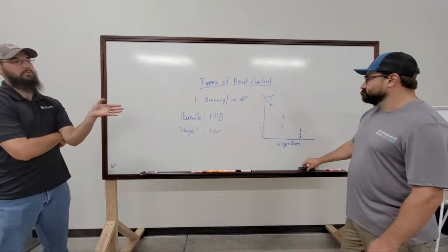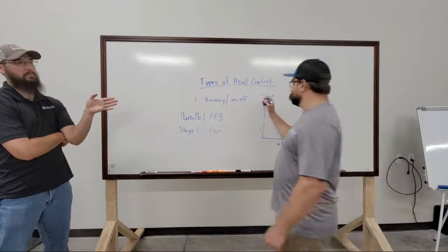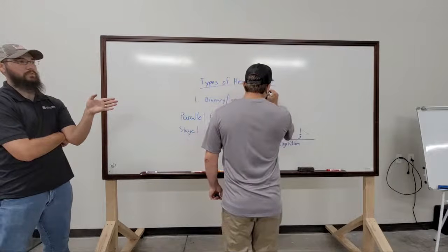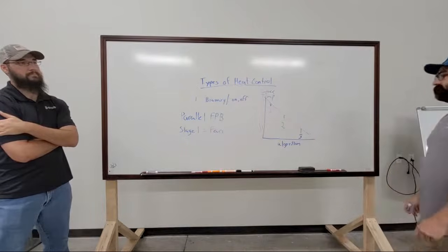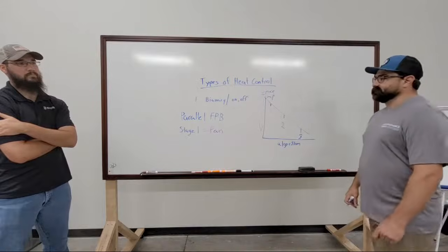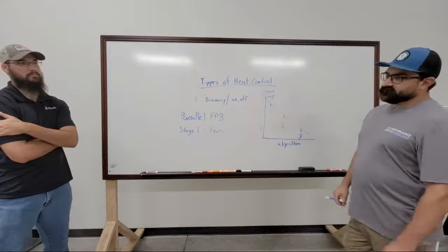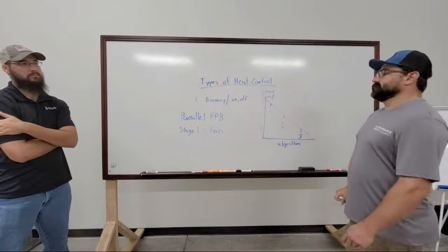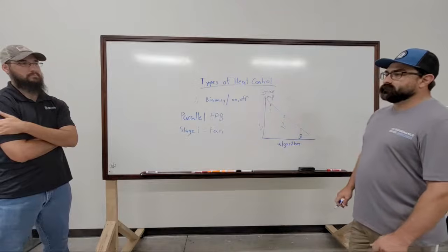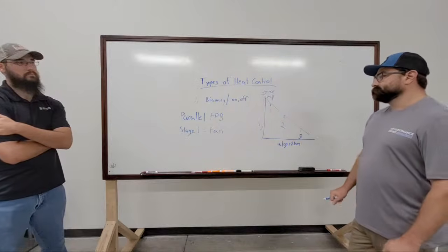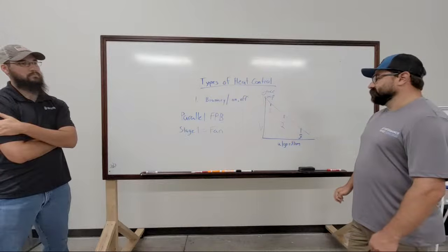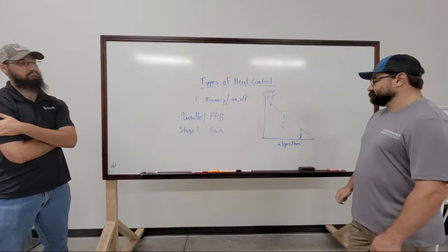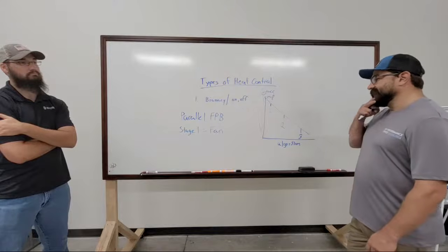And the temperature we're referring to is typically going to be a zone sensor somewhere on the wall. Space temp. Yeah. They rarely maintain discharge. There are some instances where we do, but it's few and far between. It's pretty rare, actually. I'm trying to think of anywhere I've ever done it.